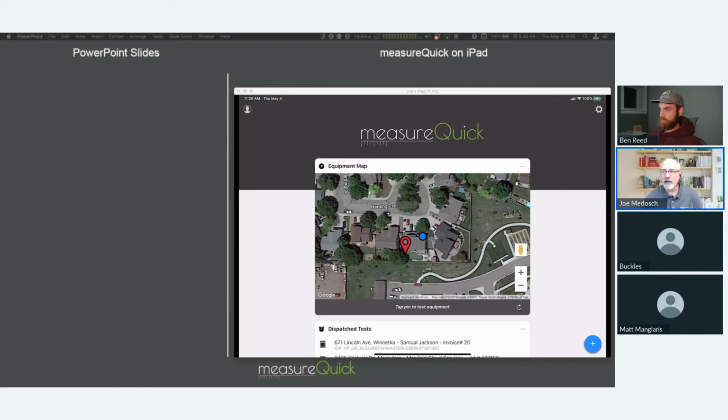That's correct. So even if you had a benchmarked system and you used non-invasive, you still don't get a score. We just felt that you needed to have all 9 probes to get a score. We realized that was a mistake in the beginning, because we thought it was good information, but really it's all or nothing. The reason is some people could cheat the system, or other people just didn't know that they didn't have accurate information. But you're right, doing non-invasive is better than nothing. It gives me a variety of information that I can make some determinations about the system, and combined with your visual assessment, probably gives you a lot of information that other technicians were still missing. Thank you. Sure. Thank you, Matt.